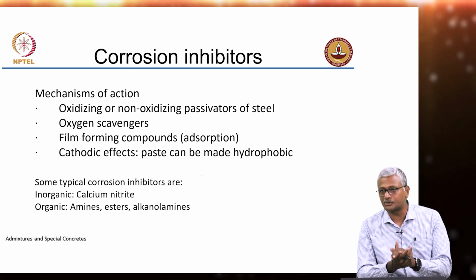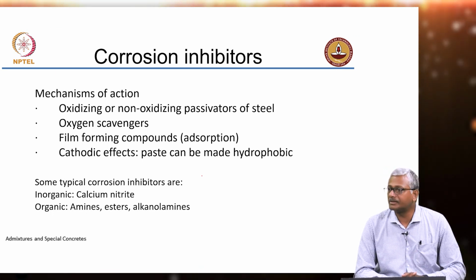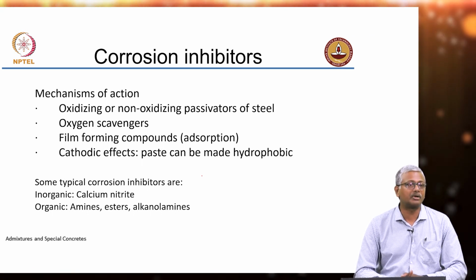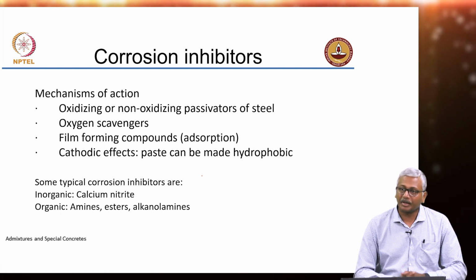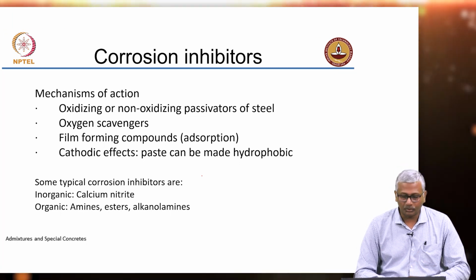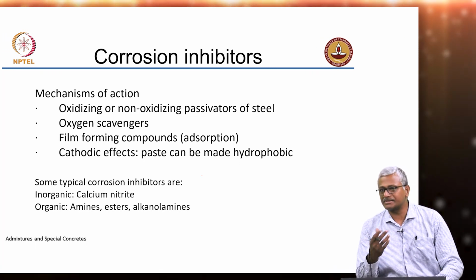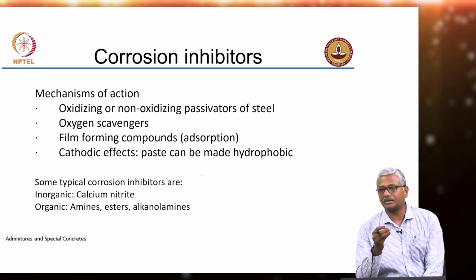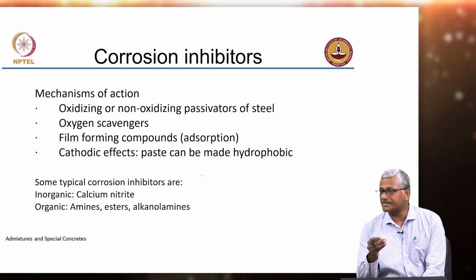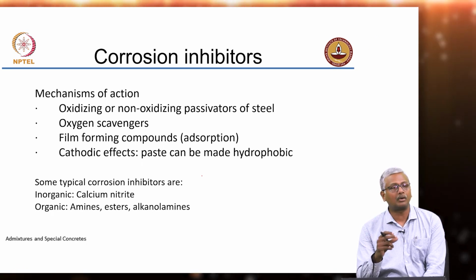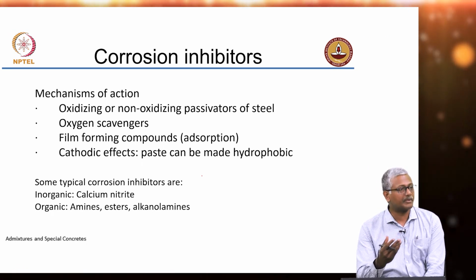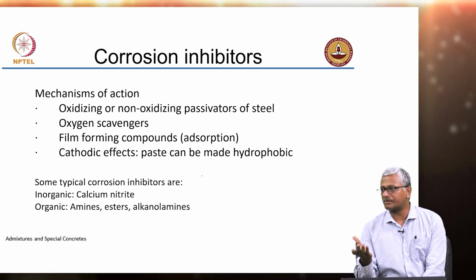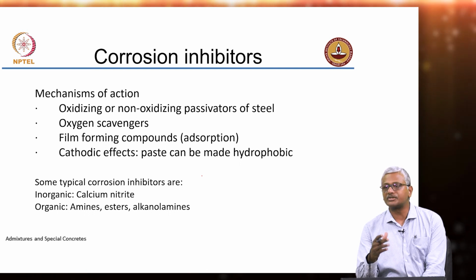In actual practice also they have seen sudden failures of fusion bonded epoxy coated rebars, primarily by pull out. So, because of this, people realize that oftentimes protecting the concrete or protecting the steel by using higher quality concrete is a much cheaper and much more viable option. One way to do this is obviously to reduce the water to cement ratio of the concrete.